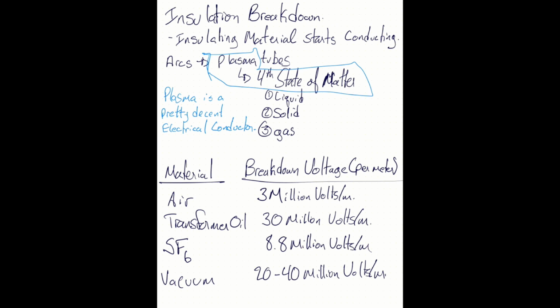Right now, the energy you can deliver through a receptacle in your home is maybe 1,500 watts. More than that under fault conditions. Under normal conditions on a distribution feeder, you're delivering 28 million watts of energy, orders of magnitude bigger, which is why we can sustain these big arcs. Under fault conditions in the city of Chatham, for example, if you get a fault on the north end of town, you could be looking at 600 megawatts of energy. That's most of a nuclear reactor being dumped into that little tiny arc, which is how we're able to hit those big temperatures.